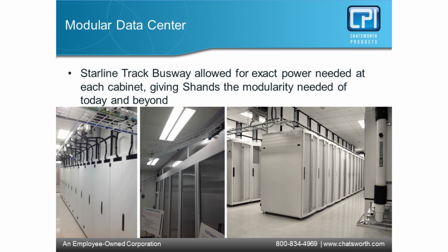Whenever folks ask me which one's better, from my aspect as an end user running the systems, hot aisle containment. If I open up the raised floor in hot aisle containment, it doesn't impact my cooling capability, so I can go through and do this future build.